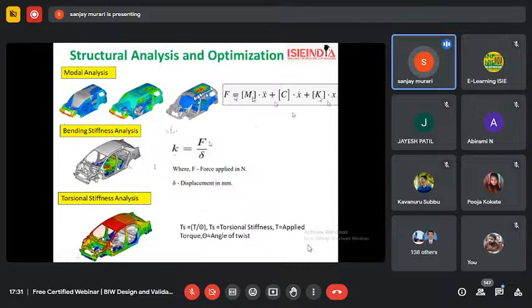We will know the length of the vehicle horizontally. At the center we are clamping, so half of the distance of the vehicle we will know, and how much deformation has occurred in the Z direction, that we will see. From that, if we apply tan theta, we get half of the distance of the vehicle divided by the deformation of the vehicle in the Z direction. From tan theta, we will get theta.